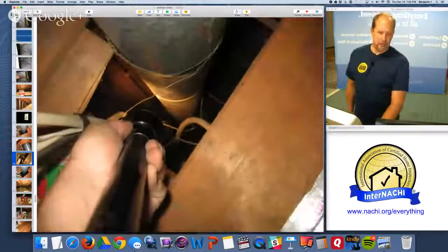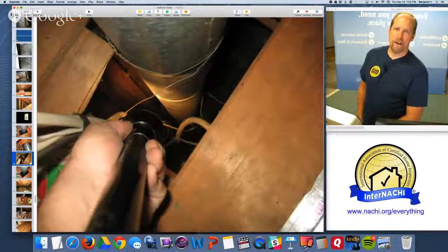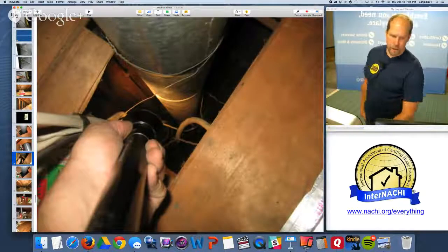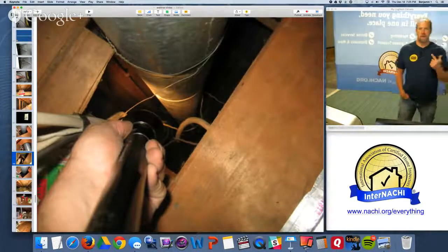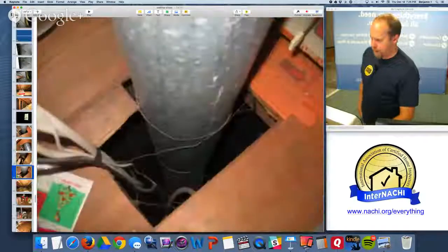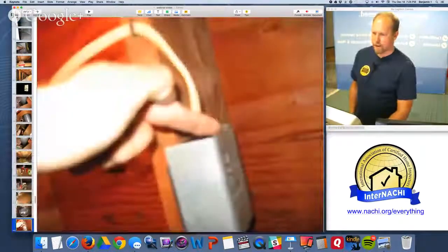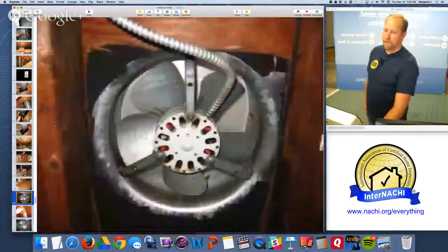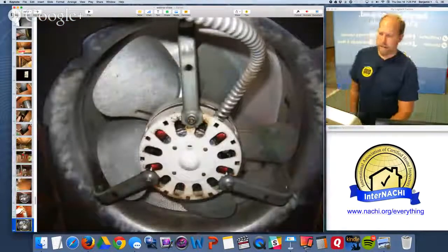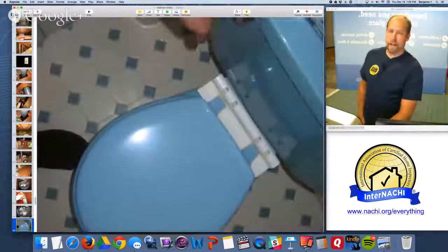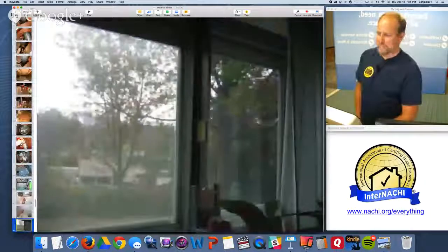there it is. There's that chase. And it's not even supported really well. They have clothes hanger wire holding and securing the unit. And there's interior cable, electrical cable, in contact with the hot flue pipe. Really dangerous situations. All right, so there's the attic. The fan did not turn on for me, the manual fan. It's on the thermostat, but you can manually turn it on, and it did not kick on for me. So not ventilated well.